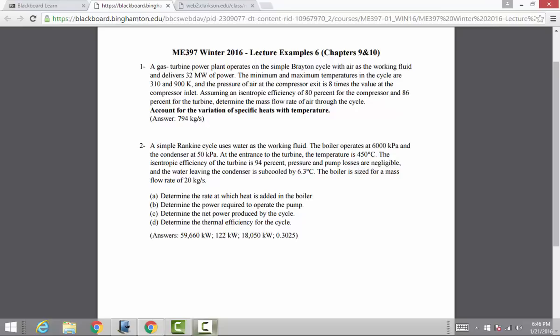So if you multiply these two parameters, m dot times little h, how would the units be? For m dot it's kilogram per second, times kilojoule per kilogram. So the kilograms cancel out, and you'll end up with kilojoule per second, which is power.